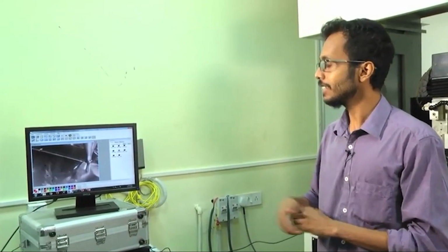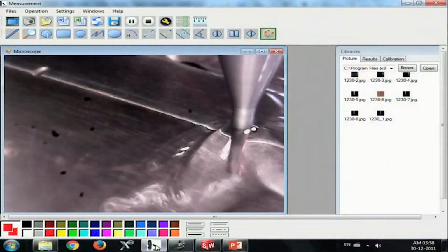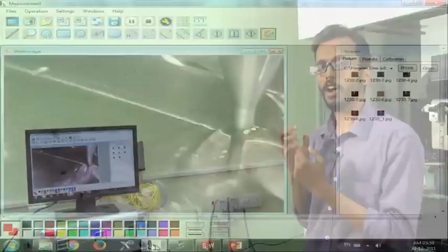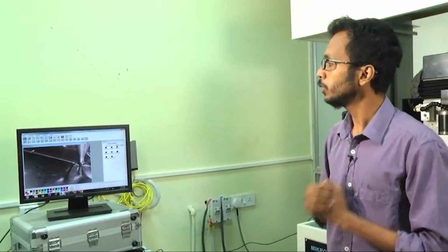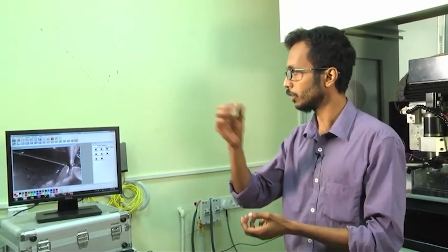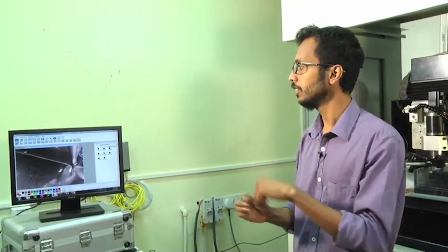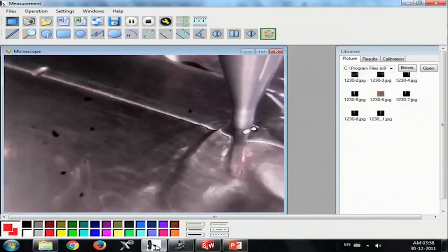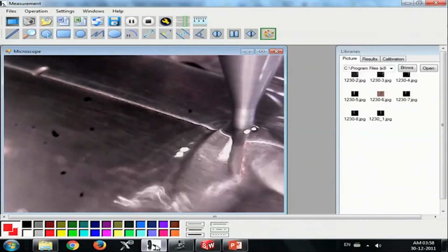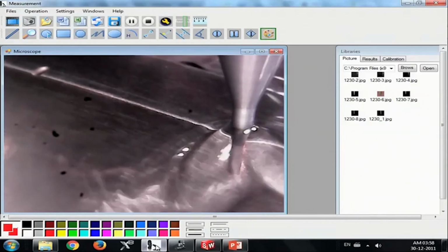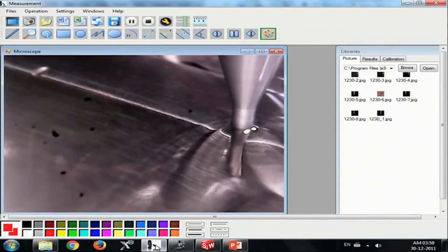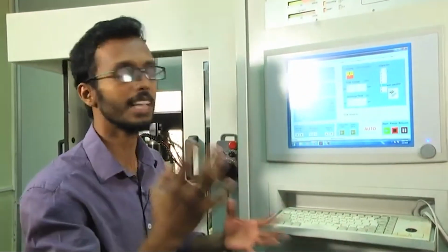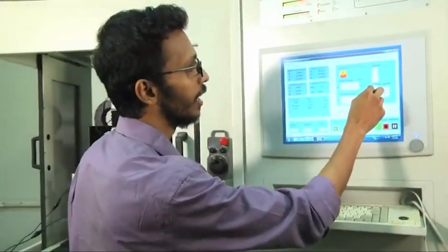So as it goes 150 micron and moving in the Y direction, the diameter will be changing from 0.5 mm to 0.2 mm, and we will be reversing the tool down and flushing the fluids on the tool blank. So to explain what happens if I am changing the machining parameters, I can explain to you. If I am changing the electrical power here, you can see that the discharge energy increases, or the spark intensity is increasing.